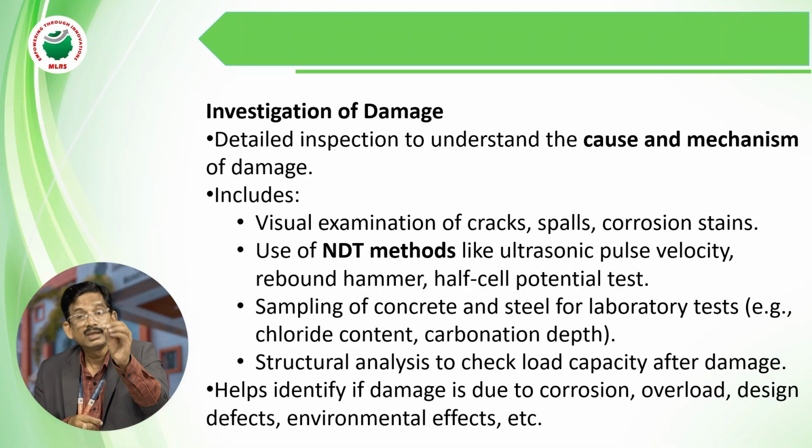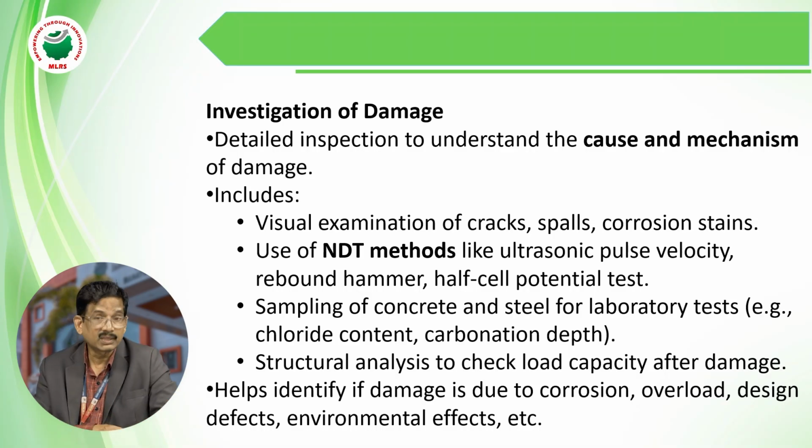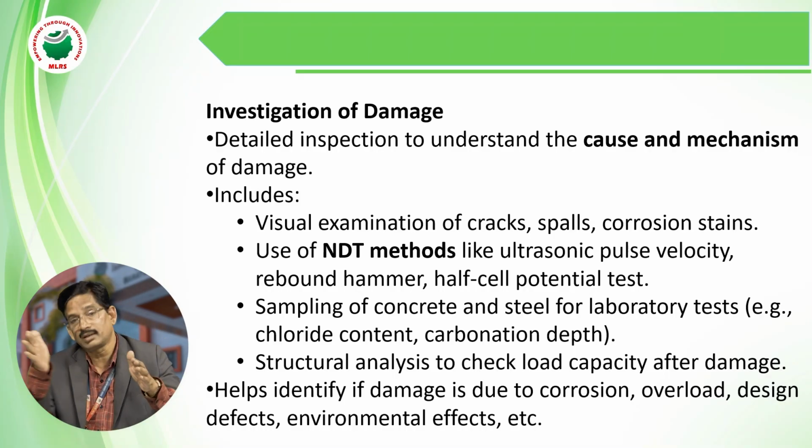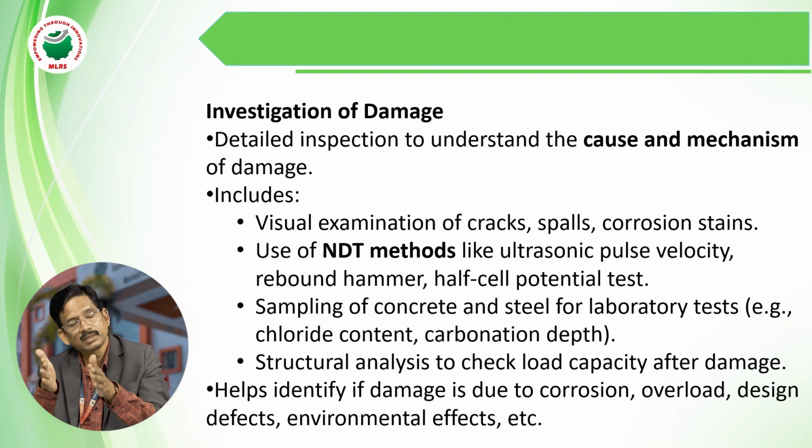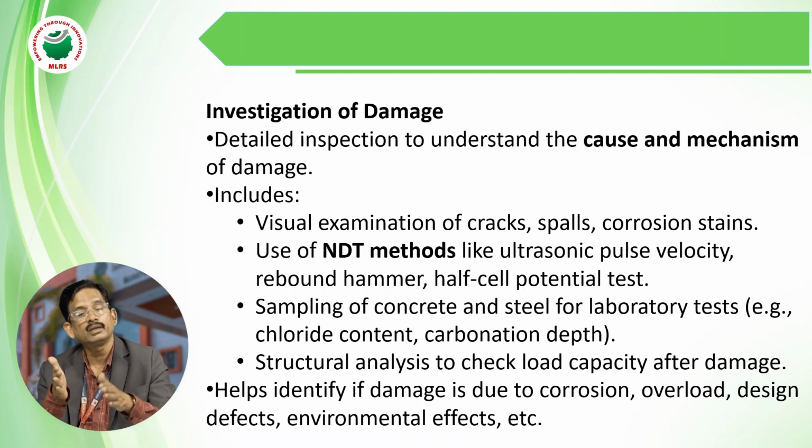With the help of the rebound hammer test, we have to test the original compressive strength of the concrete at a particular day or a particular time, whether it matches the original drawing or not, or the executed grade or not. We have to know that.